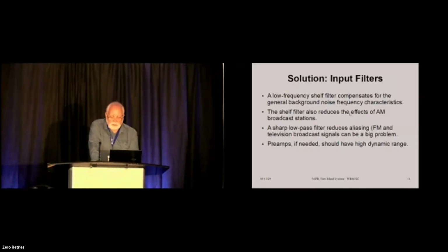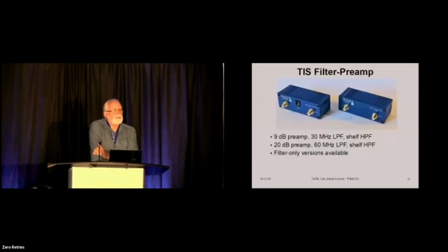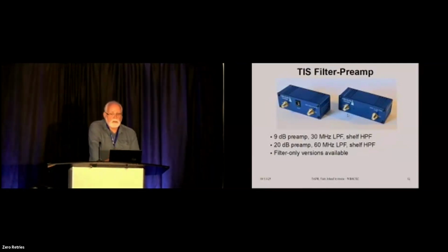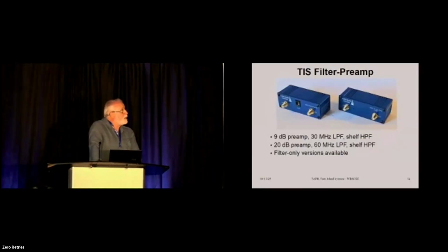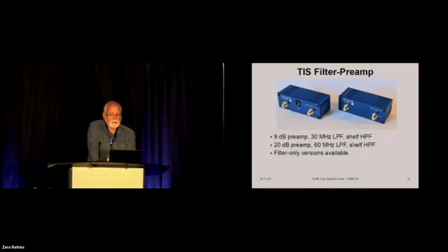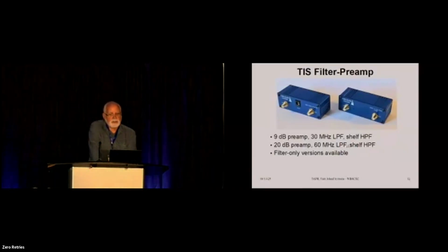I got some with preamps. In a lot of cases, we use a preamp because the ADC and a lot of SDRs, their sensitivity maybe isn't what it could be. So a little bit of preamplification is good. Too much is definitely not good, but the proper amount of preamplification can really improve things. Yeah, there's a filter or a filter with a preamp that I do. Notice the little blue boxes. That might have been the hardest part, getting the mechanical stuff done.